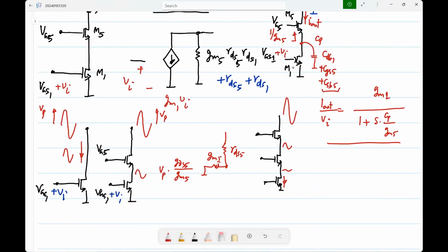No, it depends on the size of the transistors, right? No, it is the total parasitic capacitance from there. How it is related to the layout, and how you apportion something to M5 or M1, depends. So you are talking about that junction probably being shared. It may or may not be, depending on how you lay it out. But it's basically the total diode parasitic capacitance from there. If the widths of M1 and M5 are different, you cannot share it like that. They'll be separately laid out and connected.